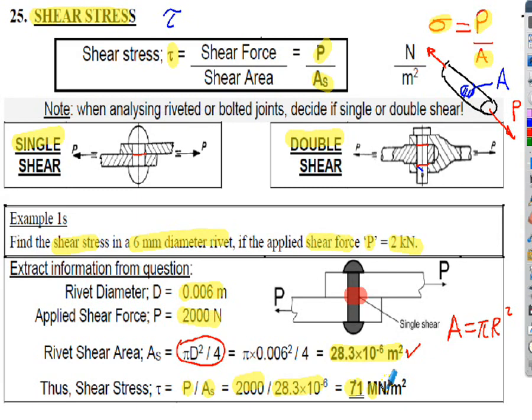And one thing to note about shear stresses is that the area you're interested in, the shear area, is parallel to the force. So go back to this diagram here, you can see the force is in this direction, my P is in this direction, and the area is parallel to that direction of the force, that line of action of the force. When we were looking at the direct stresses over here on the right hand side, the force P was normal to, at right angles to, the direction of the area. So that's why it's called a normal force or an axial force, direct force there, and this is called a shearing force, because the lines of action of the areas are, if you like, in different directions. I don't think it makes any sense to you, but that's the slight difference between the two stresses. But anyway, let's have a look at some calculations here.